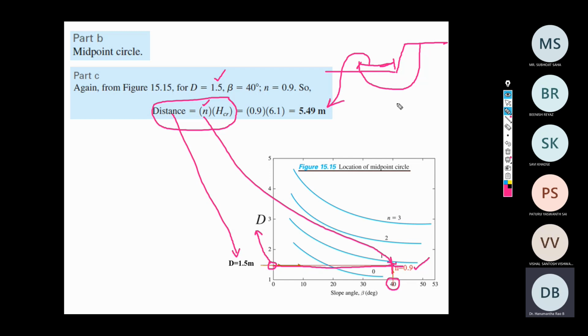But when you go for parametric variation, then you may find a little difficulty, because in reality I do not know what is the height of the slope. So my first problem is what will be the critical height. For that you need to do a lot of trial and errors, and it is also necessary to fix the value of beta, that is the slope angle corresponding to which the height is critical. So in a sense you can also draw a relationship between beta versus the critical height.